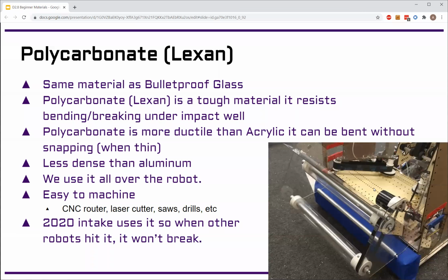It was a rather large flat piece of material. So if we used the same part in plastic or aluminum, it was going to be heavier. Or if we tried to make it lighter by making the part a thinner piece of plastic or aluminum, it might start bending or sagging in the middle, and we didn't want that to happen. So using the advantages of the wood allowed us to get the properties we wanted in the specific area of the robot.